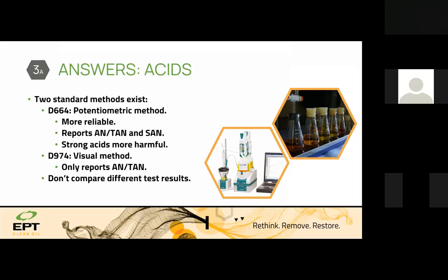So I recommend, if your application is very critical, do it based on ASTM D664 only, and don't go for D974. It's very important that you should not compare the results of these two tests. These are different tests, and we need to keep this in mind if we give the same sample to two labs to check.